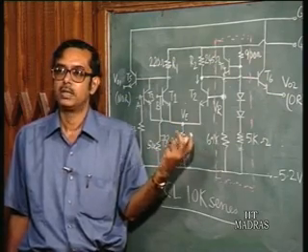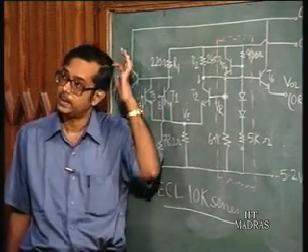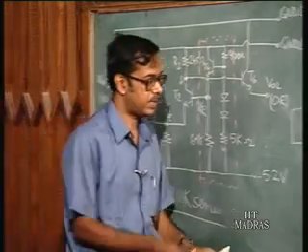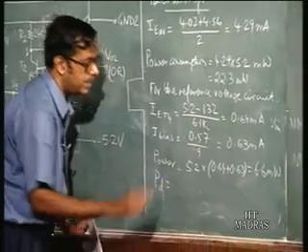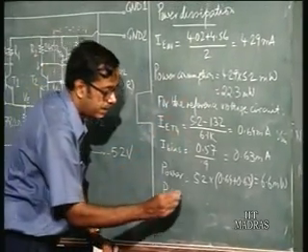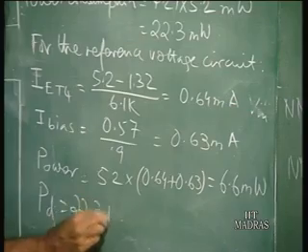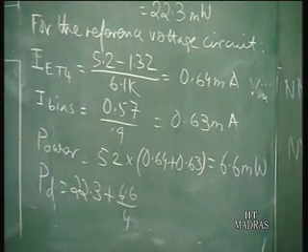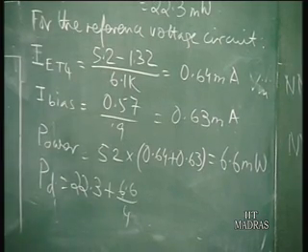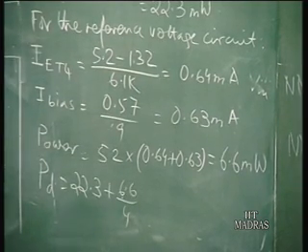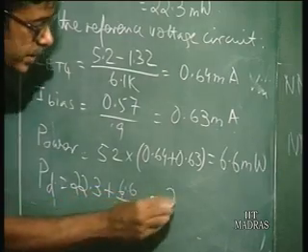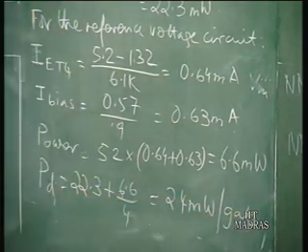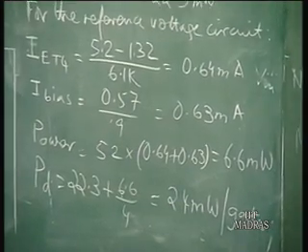So, now how do you calculate the power dissipation per gate? The power dissipation is going to be 22.3 milliwatts plus 6.6 divided by 4, because the 6.6 milliwatts is shared in the 4 gates. So, this works out to 24 milliwatts per gate.